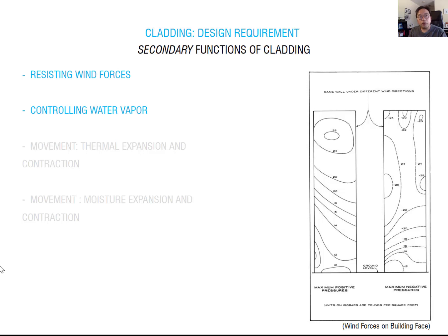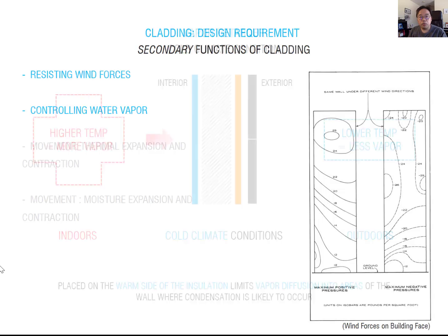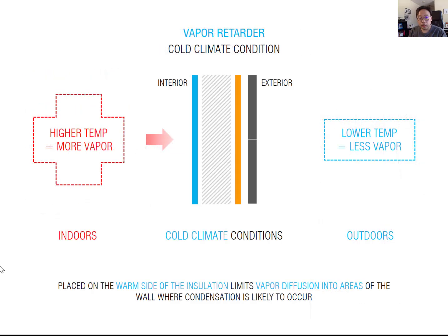And then you also have to control the water vapor. Water vapor is caused by possible condensation. So water vapor relates to moisture transfer. Moisture moves from inside to outside, outside to inside. It can cause loss of insulation value, metal corrosion, and wood decay. You probably remember this diagram. You remember dew point, right? We talked about this from the last semester.